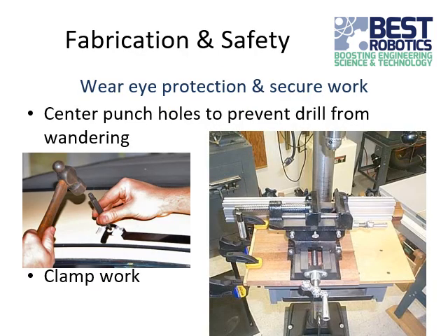For drilling, and this is especially true if you're using a hand drill, it's a good idea to center punch your holes ahead of time. What that does is put a little divot there that the point of the drill can rest in when you get started. Otherwise, the drill has a tendency to wander, as they call it, or walk around a little bit before it really starts digging into the material.